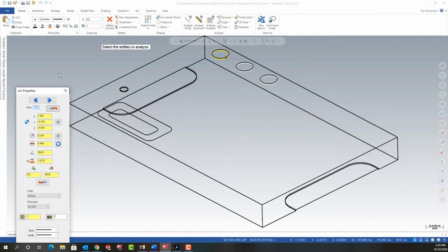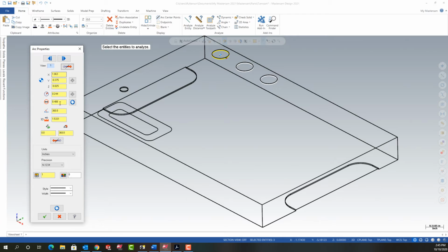And this has popped up, so I'm going to put the proper diameter here. The center point won't change, and the Z won't change, but the diameter will. Instead of 0.488, it's 0.438. I'll push Enter, and it'll apply that one. Then I'll just go Next.